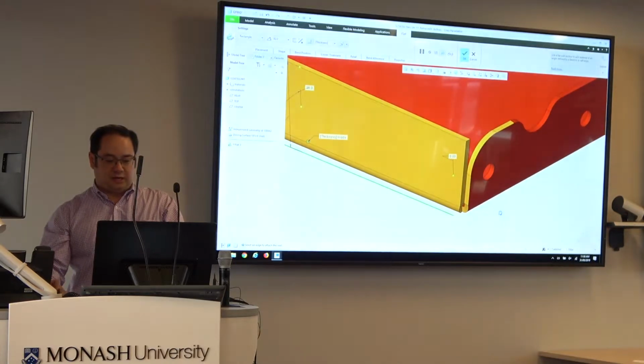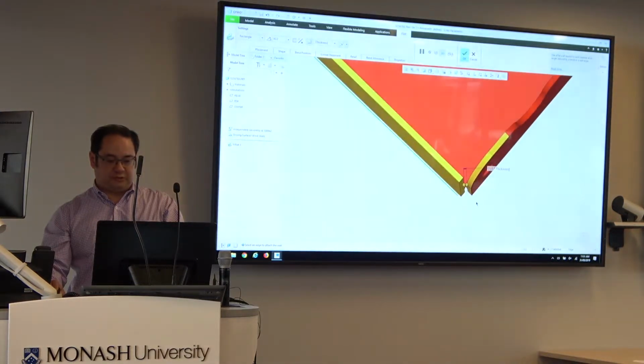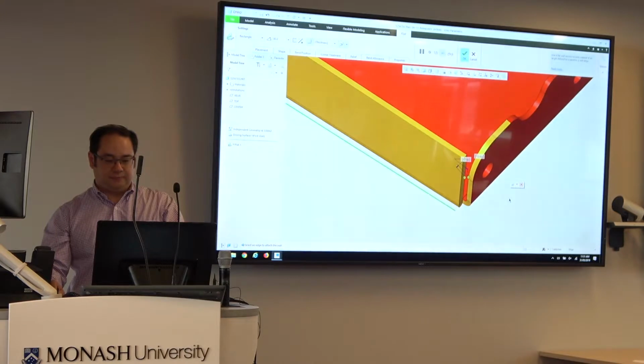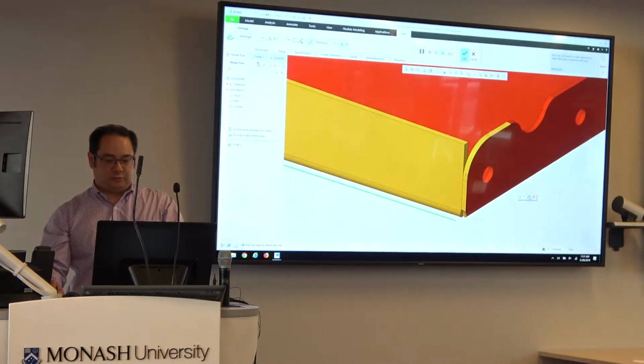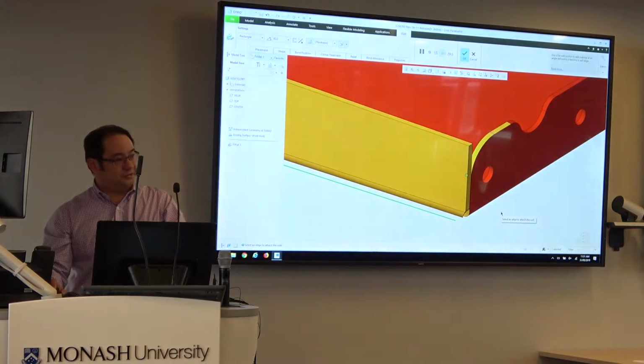Okay, I have the option, if I want to, of editing that seam. The default is open. Maybe I want to put a gap in there, or I can define a distance between them, which is just the straight line distance. Or maybe I could define a blind, so I can define my X and Y directions for that gap. Or maybe I could say I want them to overlap. So I want to extend that wall out, or maybe that wall should be extended out to overlap between the two. This is all stuff you could do in earlier versions of Creo.